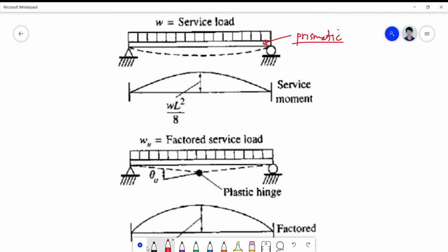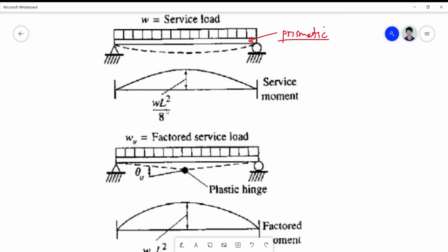Okay, so here is now your beam allowed to what? Ito yung sinasabi ko sa iyo na yung plastic analysis class can be accounted for by factoring the service load. Kita niya, no? Factoring. Although this is not basically giving you the actual plastic analysis per se, but it can actually approximate the increase in the service loads to the inelastic or plastic load by way of applying the factors, the overload factors.